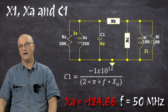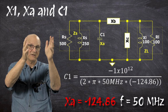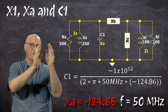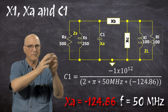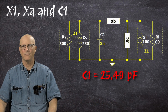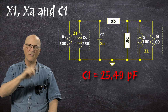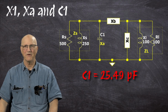That gives us C1 equal to minus 1 times 10 to the 12th divided by 2 times pi times 50 megahertz times a negative 124.86, which gives us a capacitance value of 25.49 picofarads. And this is almost exactly what we got with the Smith chart. Now, on to the next component.